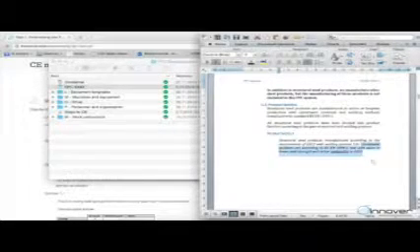Depending on how many welding processes you have, that determines how many product families you have. For example, if you have only MAG welding, you define the product family as those steel products according to EN 1090-2 that are made with welding process 135. So this is the official number for MAG welding. The rest of this is just standard text.